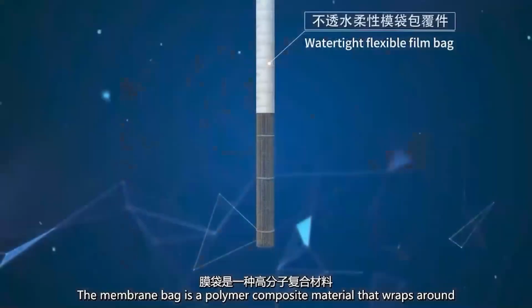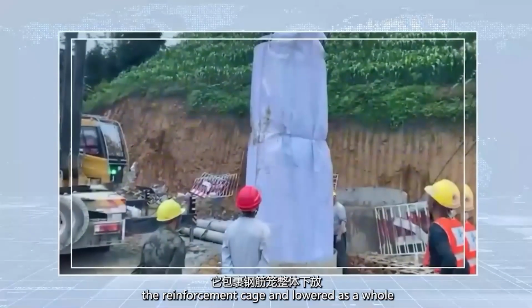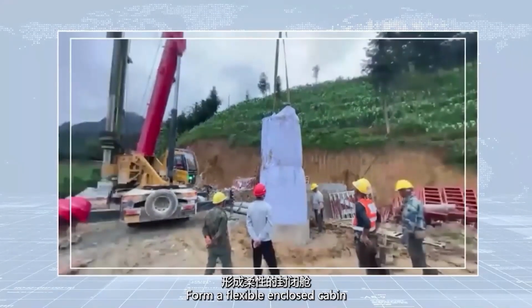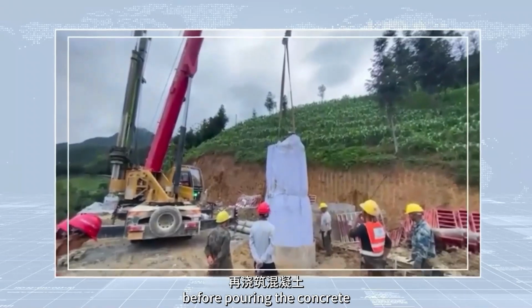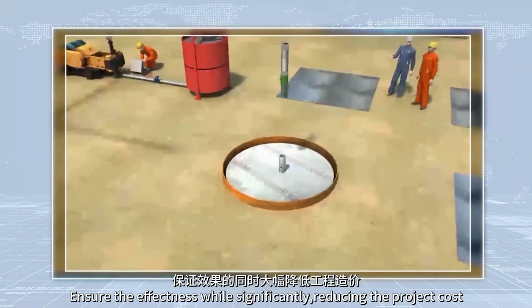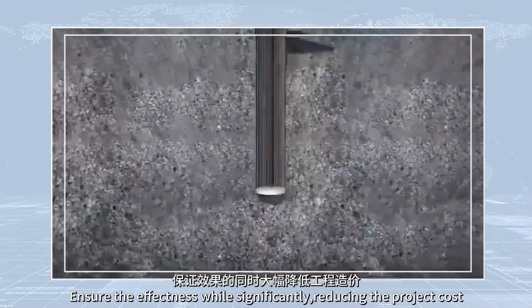The membrane bag is a polymer composite material that wraps around the reinforcement cage and is lowered as a whole to form a flexible closed chamber, preventing the concrete from overflowing before pouring. It ensures effectiveness while significantly reducing the project cost.